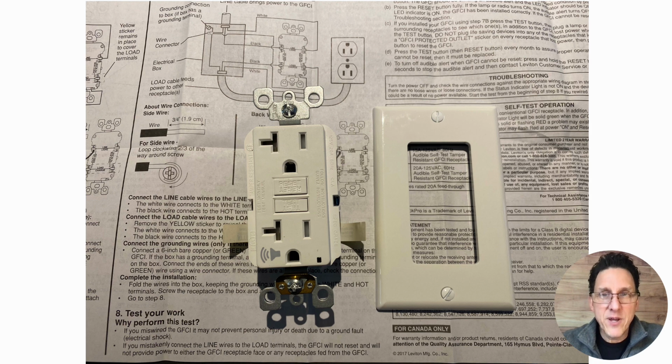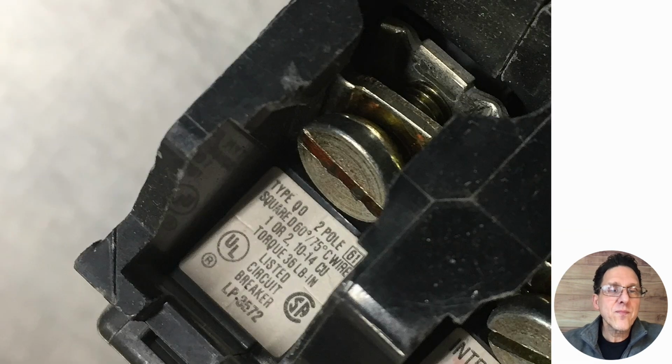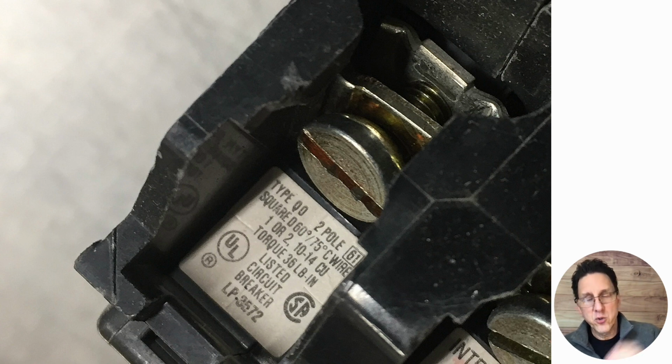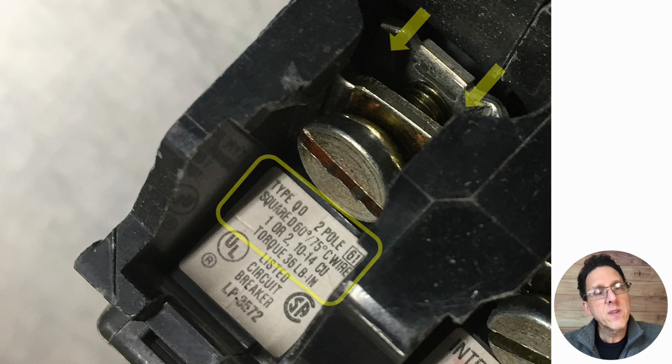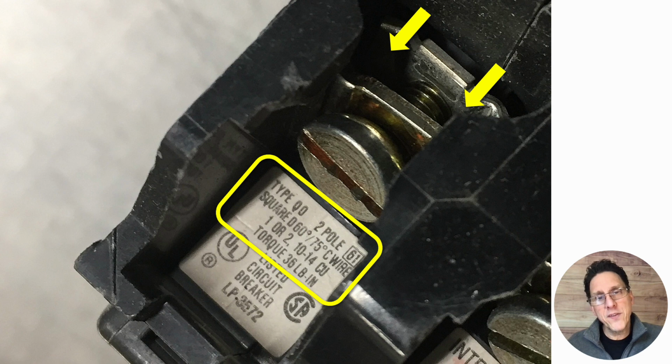Okay, let's take a look at some other stuff now, all right? So this is the terminal for a circuit breaker, right? There's a little label there where it says UL and CSA and a bunch of other information. All right, and some manufacturer information. So can we put 3 wires under this terminal? No, we can't put 3, but we can put 2. According to that label, it says we can have 1 or 2 10 gauge, 12 gauge, or 14 gauge copper wires. Not aluminum. It doesn't say we can use aluminum there, but it does say copper. And we can also use 60 degrees C or 75 degrees C. And again, that's according to that label, right?